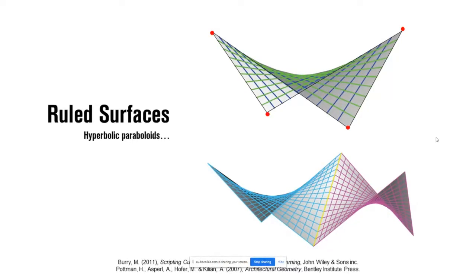and especially with concrete, because wherever it's loaded, if it's a pressure, so say if you put it on a facade, always some of the panel will always be experiencing compression. So if it's pressured from the top side, I'm not sure if you can see my mouse, but I'll try and gesture with that. If it's pressured on that top face there, the arching action will happen on the diagonal, and vice versa, if there's a suction pressure or something.